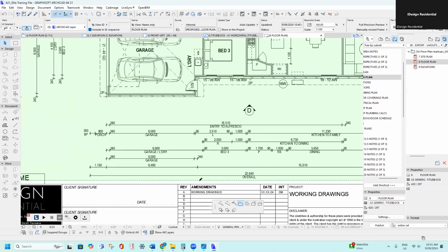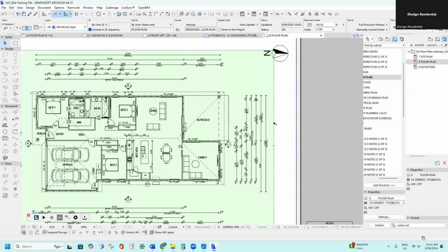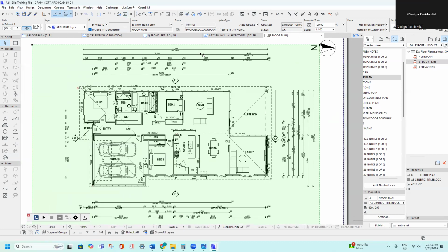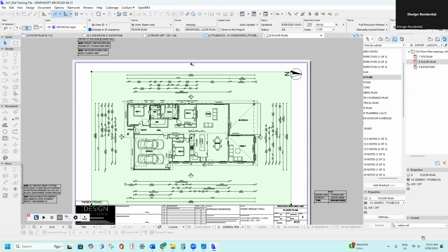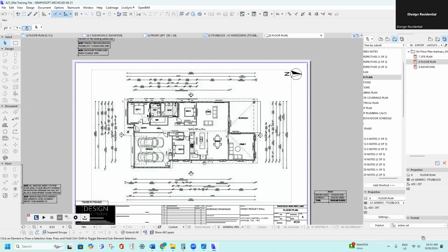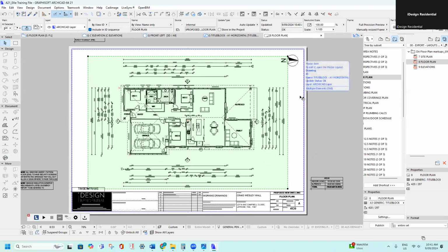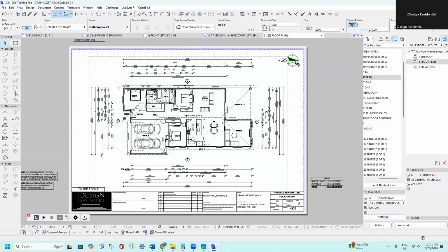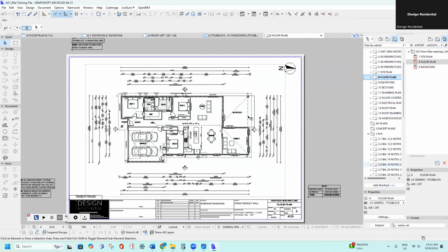So the reason that I bring in all the edges just outside the overall dimensions is so that I can then center it on the page relevant to the size of the actual drawing, the house and the dimensions. So basically it looks more centered on the page if I do it like that. That's why I do it that way. And then I have a north symbol up there, which I can cover how to do in another time once we get on the site plan.